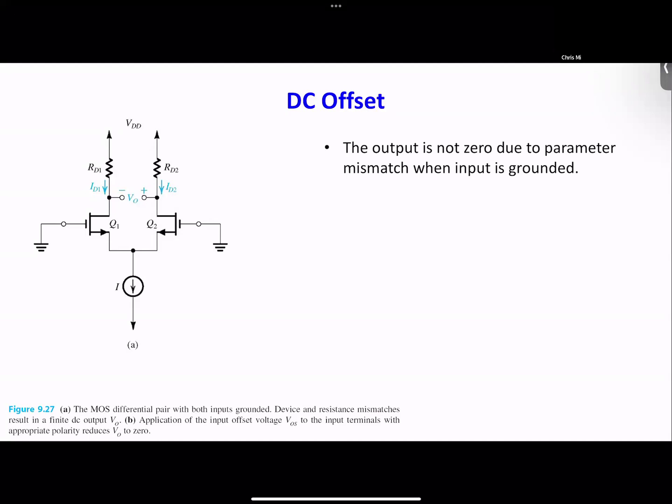But sometimes your output is so small and your DC offset gets so big, let's say your output is 100 millivolts, that's what you want, but then you've got a DC offset of 10 millivolts. Would you care now? You do, because a 10% error is introduced. So, okay, we know there's an offset and we care. What do we do then? Well, it's actually very simple.